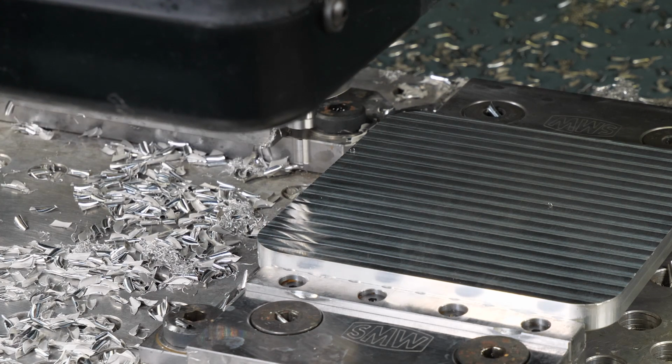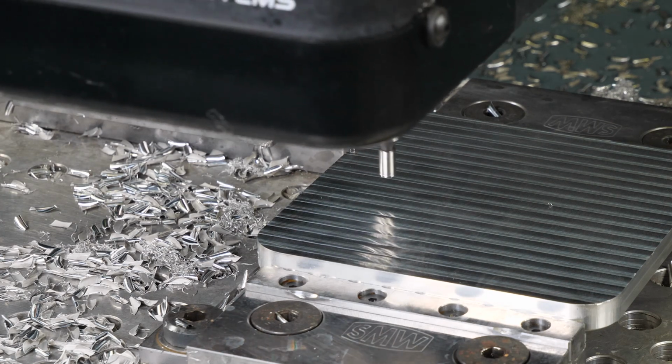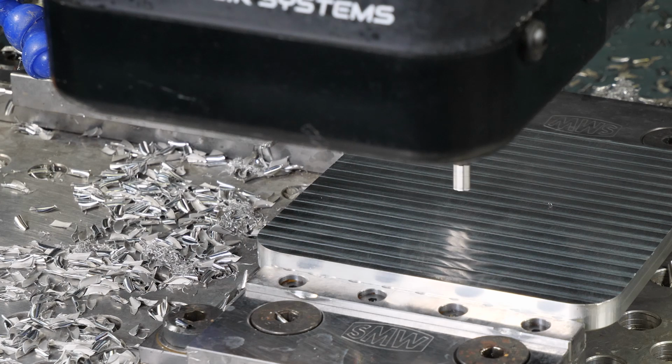There's our wobble again. So now I know the tip of our edge finder here was 200 thou. So I need to come over 100 thousandths, and that's going to be my 0. Or I can just type in negative 100 thousandths, and it knows. So I'm going to do Y negative 100 thou. Now we're going to zip on over and do the same thing for X. Excuse me, that was X that we were just touching off there.